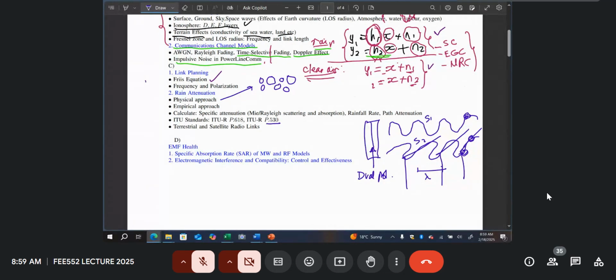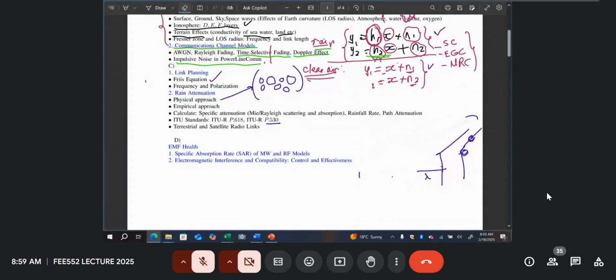So this is what you do. You analyze a certain region, and then you analyze the raindrop size distribution, because that is going to affect how these waves are absorbed within the drop. If you are transmitting at very high frequencies, the wavelength is going to be very small. So your signal could be absorbed within just one big drop. If it is absorbed, then you can't have it.